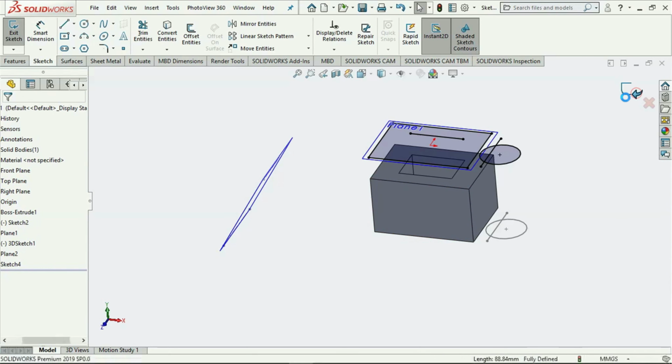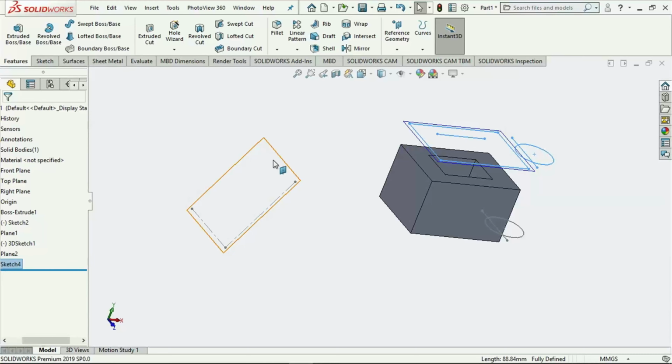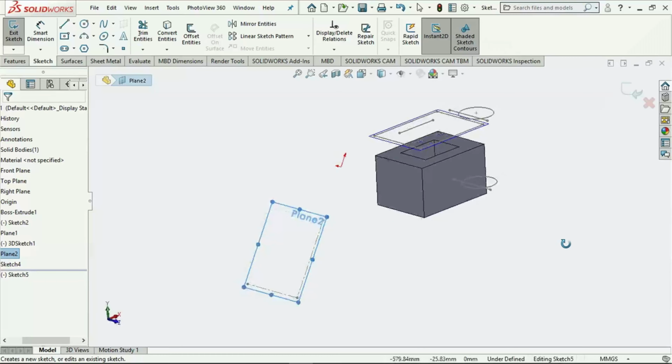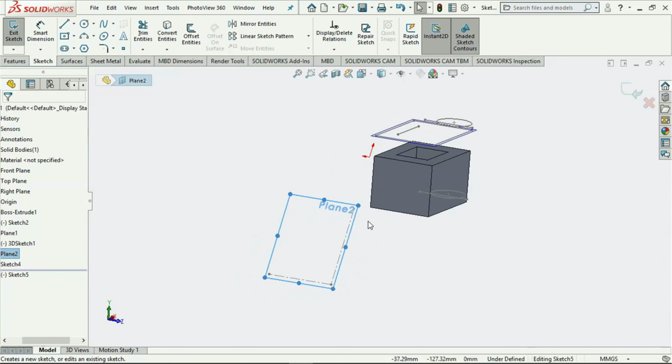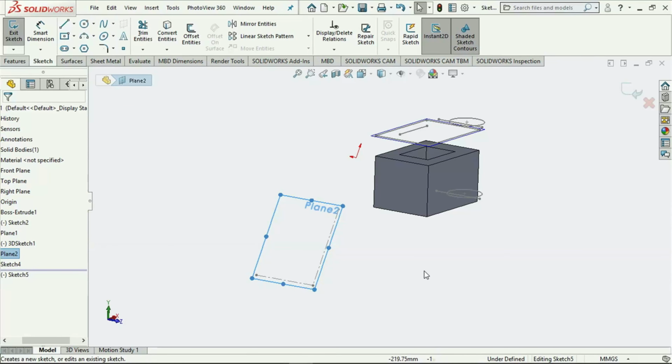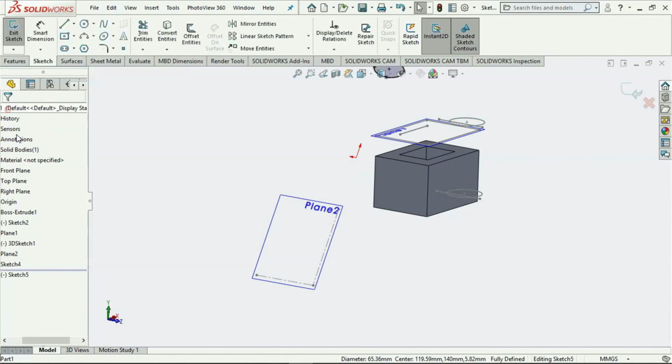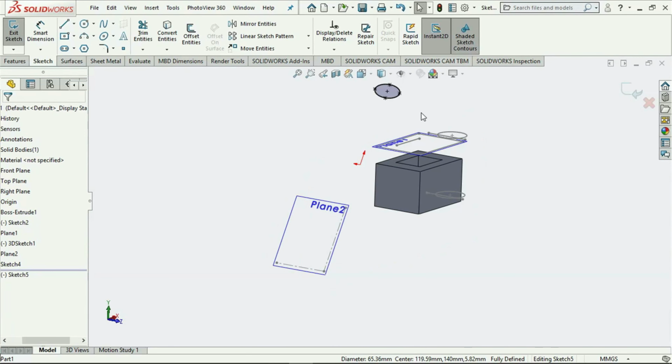This time around, I will select this inclined plane and make it my active sketch. Alright. Now remember that the plane is not limited to these four corners here, but it's actually onto infinity. So if you do not know about that, you can check the previous video on creating sketches, and then you discover that there. Alright, so I go over to the convert entities, and then I click on this circle again and say convert. And what do you notice?